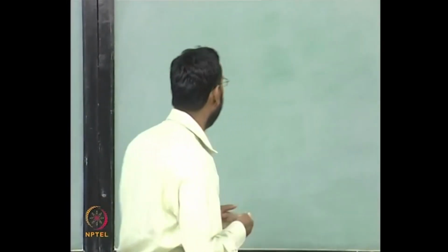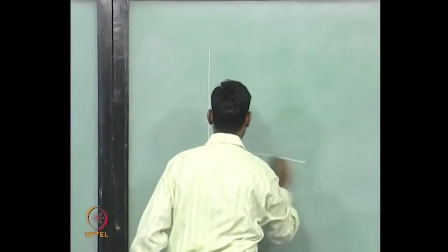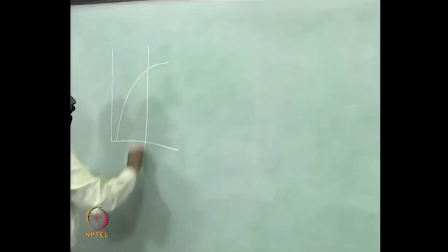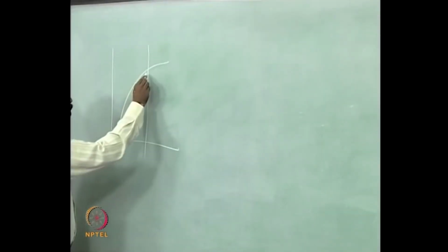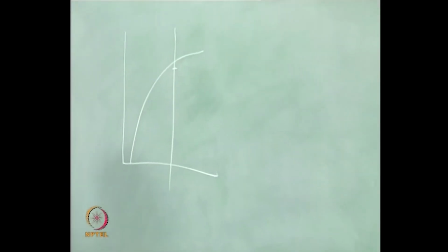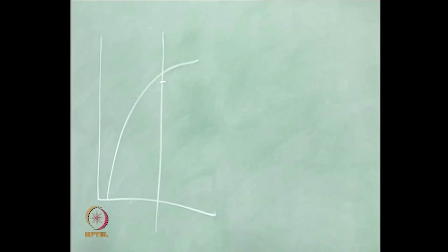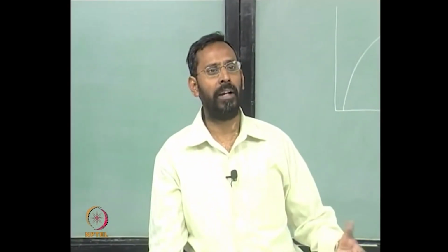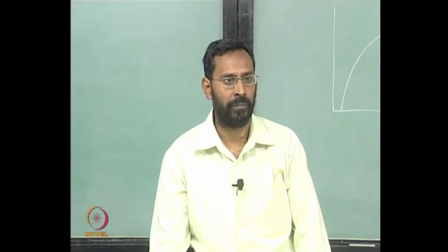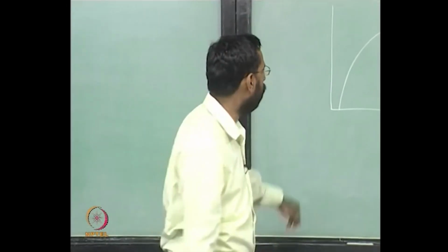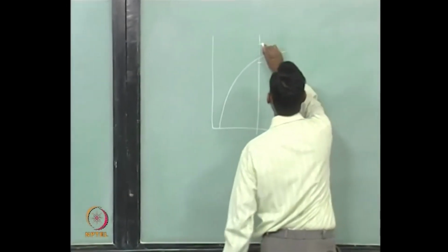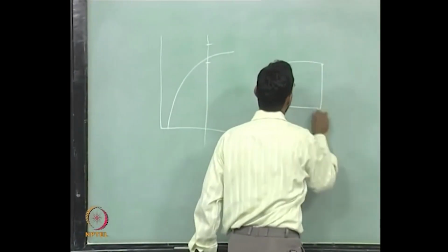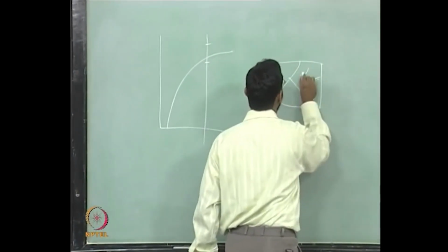If you consider any alloy, if the precipitation is taking place at that temperature, we already said that if you are just below the solvus line, you can easily have the nucleation of the second phase happening at the grain boundaries, right. So, if you consider an alloy at that particular condition, the alloy would be something like this, let us say alpha phase.